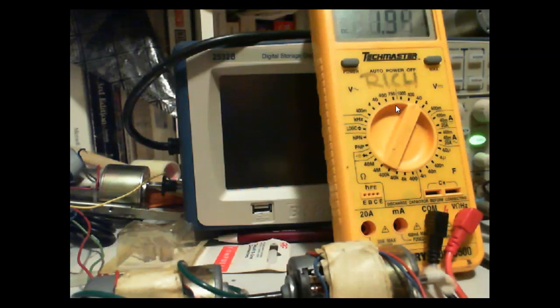So once we get our transfer function, of course now the motor is not running at all, I get 0 volts out. And even though it's running extremely slow, we still get a voltage out. So our control system can precisely control the speed of the motor by using this coming in.